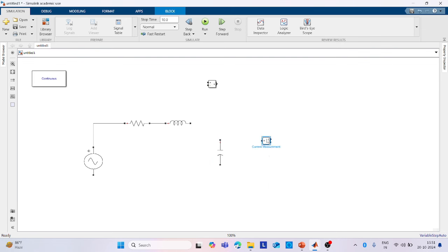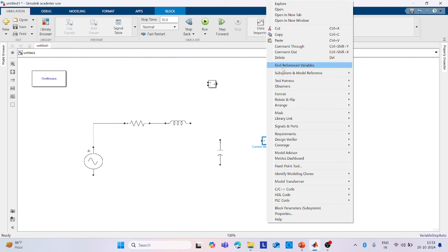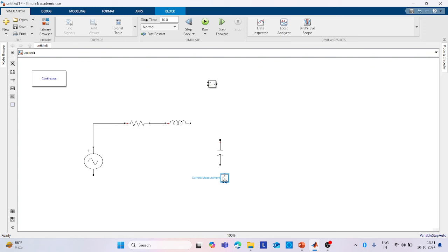And we have a current measurement. We need to put it in a proper way. The current measure is through elements. So I'll take this current measurement like this, and I'll connect it to the source by this line. Then the inductor and capacitors are closed. We should know the value of voltage across the source we are giving. Numerically we know the value, but we need to plot it on the graph also, right? So that's why I have selected this. So all these are the things.